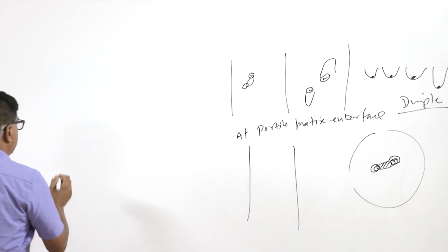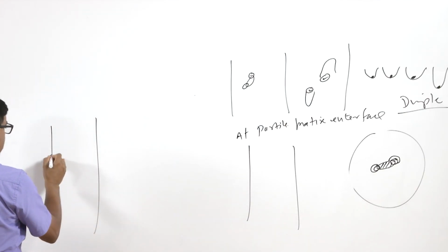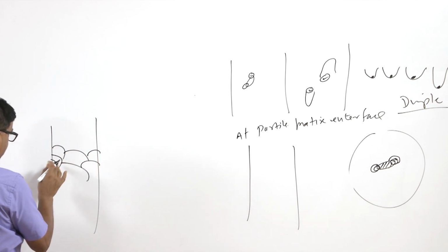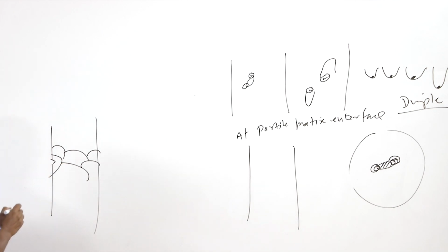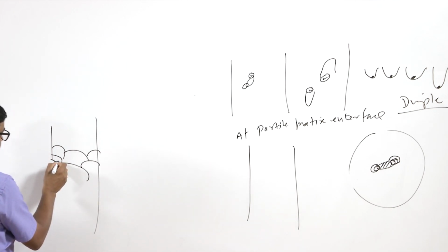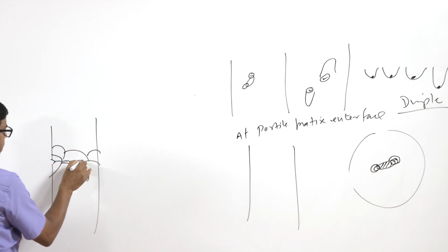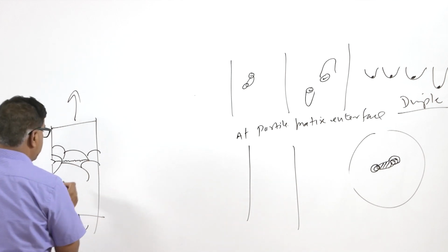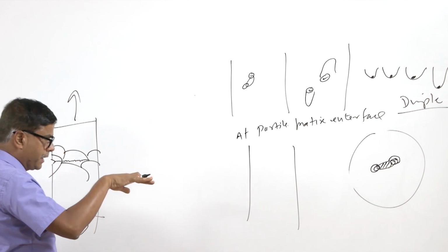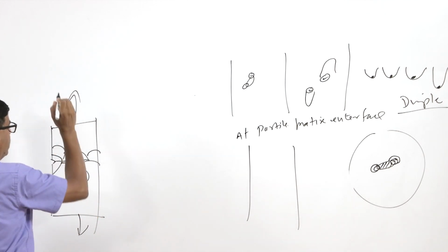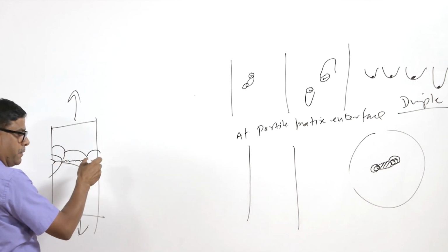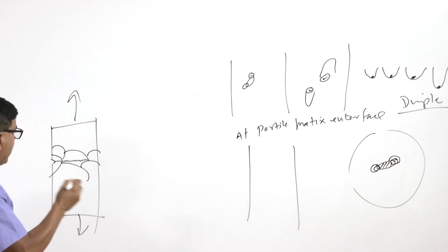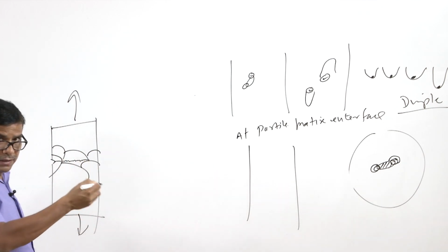There can be a situation where these are the different grains present, and if we have one crack here and it has to grow, irrespective of the phases and the boundaries, it grows perpendicular to the direction of the external load. It does not follow any particular direction, and the crack grows across the grains, it does not follow the grain boundaries.